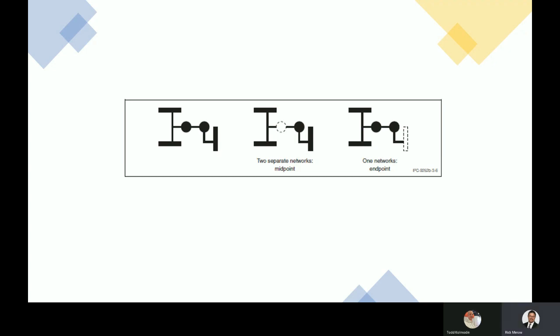Now, because current can flow from A to C, and it's straight through, whether B is there or not, you're still going to have a connection from A to C, and you still have a connection from A to B or B to C. We don't need that middle B point. Mostly this was done in the past for fixturing, to reduce some of the test points when we build a fixture. So you remove point B. That's called a midpoint.